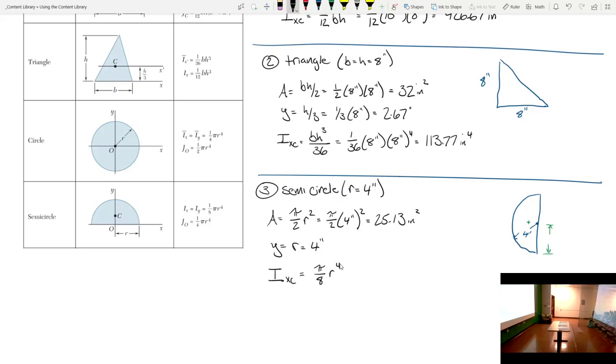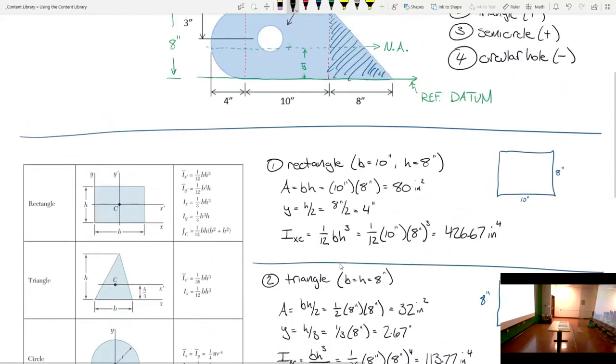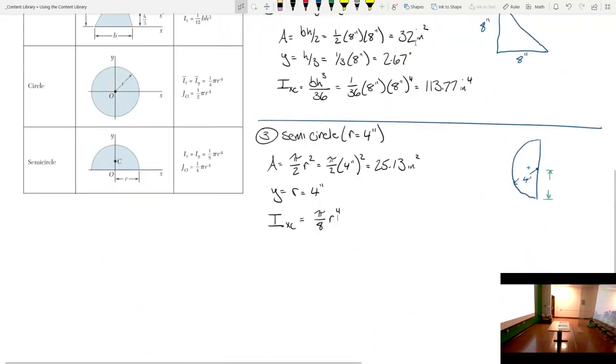Okay, I'm going to scroll up a little bit because I kind of want to make a point about something. Okay, let's take a look at this rectangle. The moment of inertia of a rectangle with respect to its centroidal x-axis is bh cubed over 12. But if I take that rectangle and I turn it 90 degrees, the moment of inertia doesn't become bh cubed over 12. It's b cubed h over 12. You flip what you're cubing. So we're kind of fortunate with semicircles here, but all I'll say is you got to make sure that you're dotting your I's and crossing your T's on your bookkeeping.